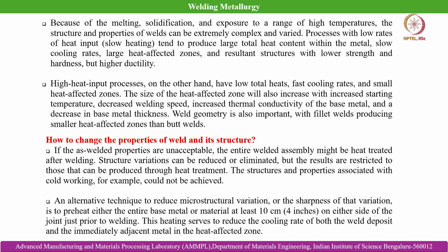There they are talking about high heat input in a highly localized manner. Because of their localized impact, the joint becomes much cleaner and the heat affected zone size also gets reduced significantly, and apart from the region where the joint formation is necessary, it hardly impacts the metallurgical structure of other regions of the parent body which are being joined with each other.